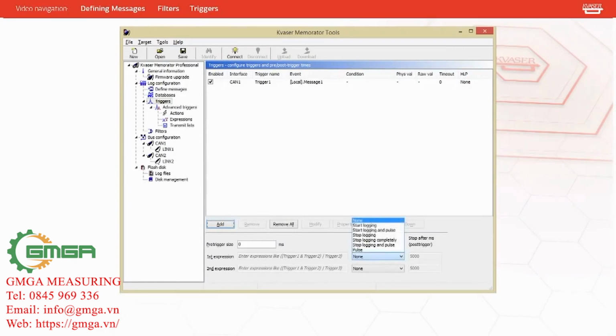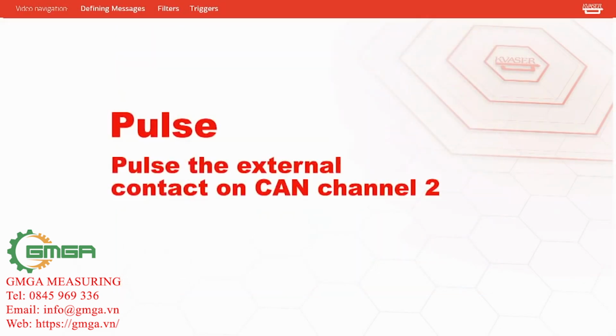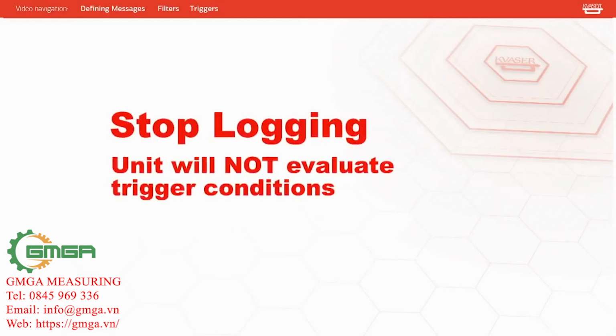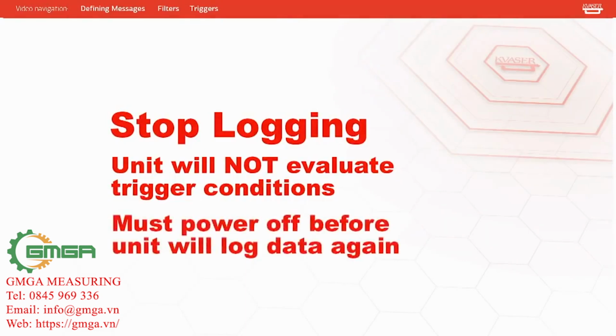start logging and pulse, stop logging and pulse, stop logging completely, or just pulse. Pulse means to pulse the external contact output on the CAN channel 2 connector. Stop logging completely means that the unit will not evaluate the trigger conditions again. The unit will need to be powered off and back on before the unit will log data again.